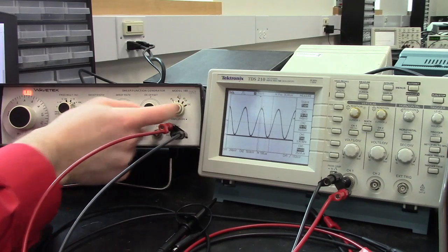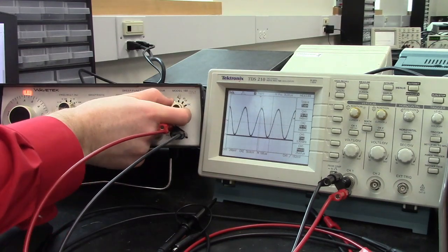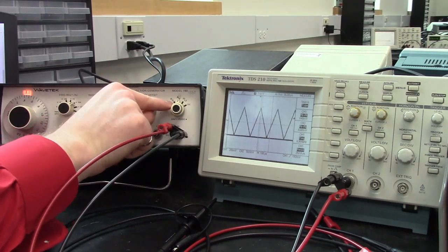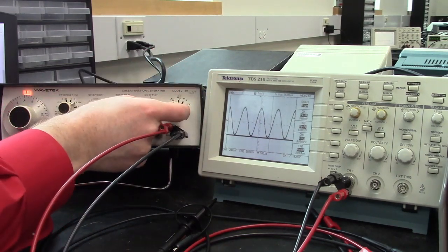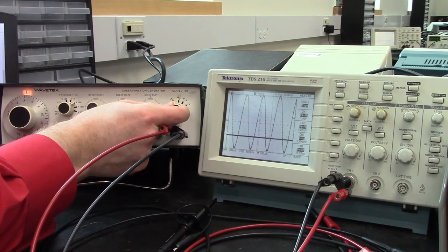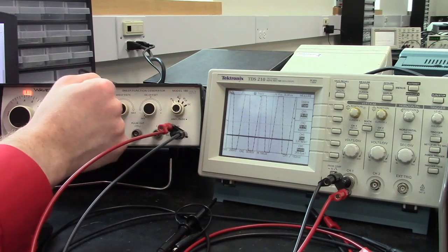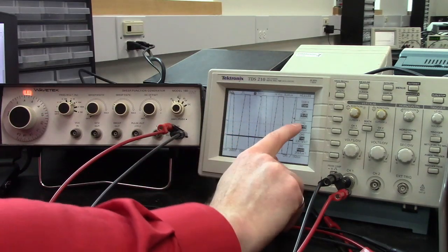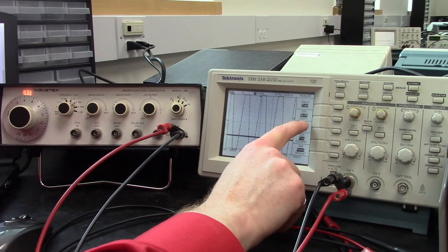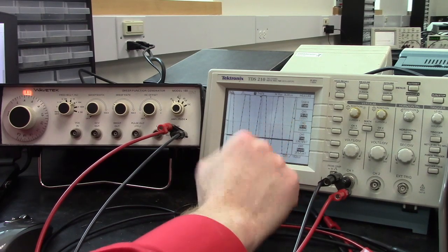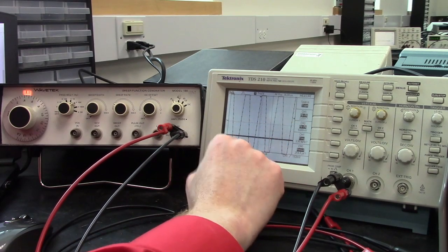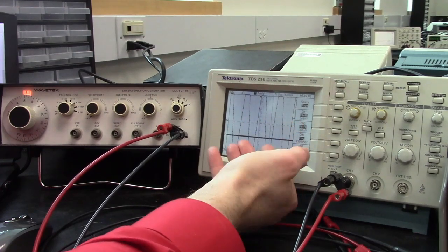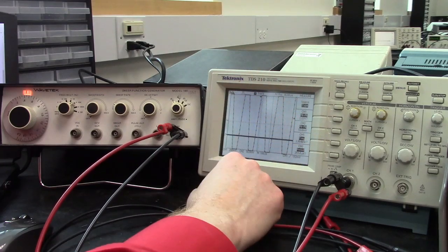What we're going to do is adjust with this knob here. So the outside one controls whether or not it's a sine wave versus triangle wave versus a square wave. But this inside one here will adjust the size of the signal. So we can increase that until we get to a 4 volt peak to peak. Now you see, because we're outside the screen range, the voltage peak to peak has this question mark afterwards, meaning that the scope cannot actually measure what's going on here because we're outside of the range. So it says it's 2.03 volts, but it doesn't know. We're off the screen here.